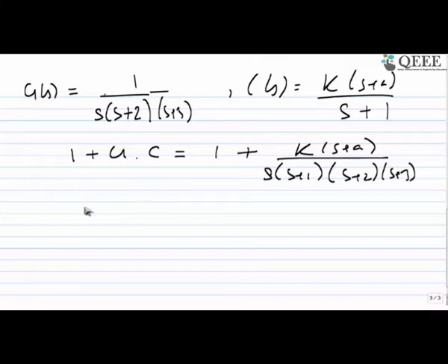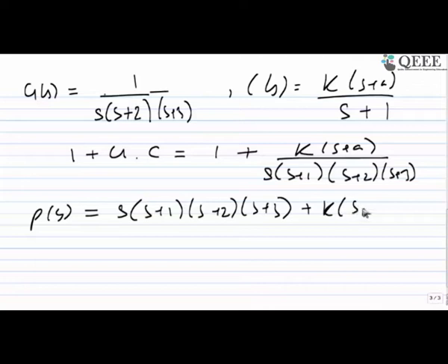From here I would have my polynomial, which I need to analyze to see whether it would be Hurwitz or not, and basically it is the numerator of this equation. I need to determine the stability, or the Hurwitzness, of this polynomial. So let's simplify this one. This would read s to the 4 once you simplify it.